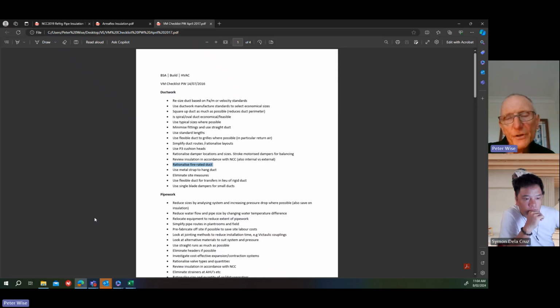But if it's a shopping centre with supermarkets, specialty stores, big bulky goods stores, the whole thing changes, because then you have to have a smoke hazard management system, since you've got a lot of people in the building. If a fire breaks out in one of the shops, you need to make sure that everyone can escape and you get rid of the smoke. So that's something to be aware of, because that's always relevant.